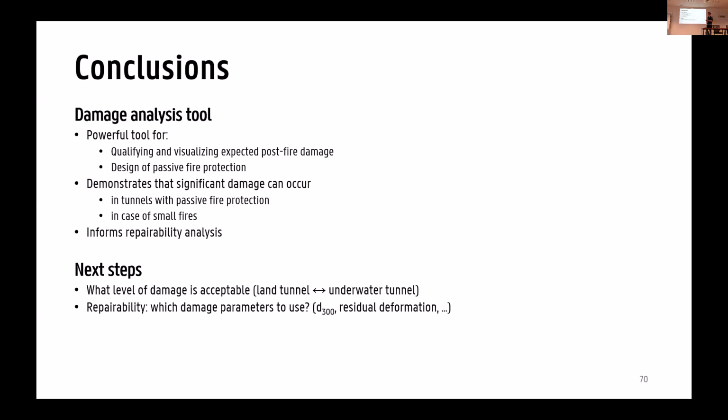So we developed a damage analysis tool because really there was a question from our client like, okay, it's nice to know that our tunnel does not collapse in case of a fire, but what to do after? What will be the damage? Can we repair it? So basically, it's a tool which can help us to quantify and also visualize this post-fire damage. And it can also actually help in the design of passive fire protection. And it demonstrates that even if you have a tunnel with passive fire protection, or in case of a small fire, there can be quite severe damage. And it can also inform repairability analysis.